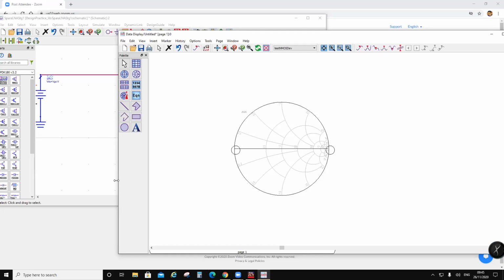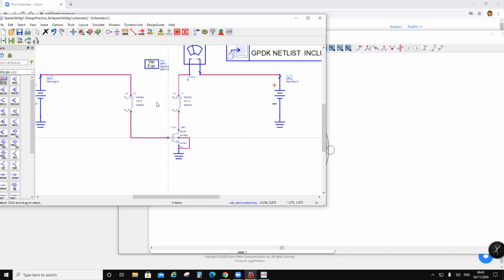People don't do decoupling, they don't do coupling, and they don't do termination, they just do the DC curves. In large transistors, this is not correct. Even in the lab, when you measure on a parameter analyzer, you'll find that large transistors tend to oscillate. So you need to terminate them in proper impedance before you take the DC characteristics. That's what I used to do.